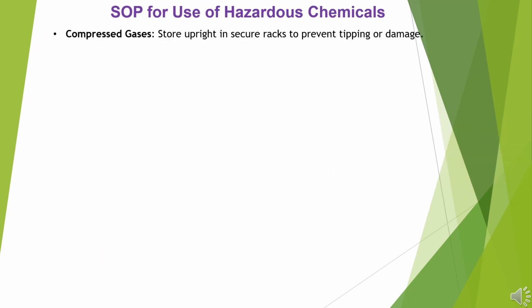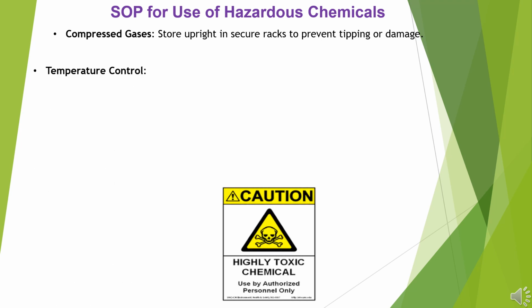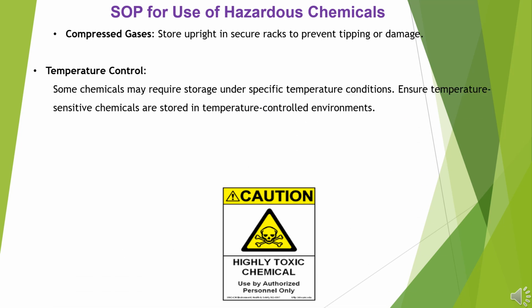Compressed gases: store upright and in secure racks to prevent tipping or damage. Temperature control. Some chemicals may require storage under specific temperature conditions. Ensure temperature-sensitive chemicals are stored in temperature-controlled environments.